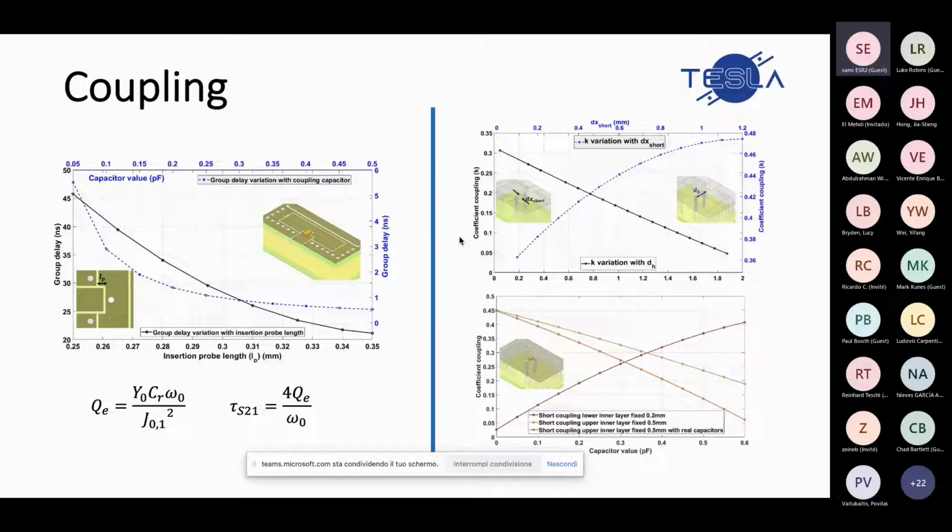The capacitive coupling is provided at the top layer by controlling the distance between the resonator patches and also by mounting SMD capacitors between the adjacent resonators. Again, the largest capacitive contribution is made by these SMD capacitors, while by increasing the gap, we can decrease the total equivalent capacitive coupling.